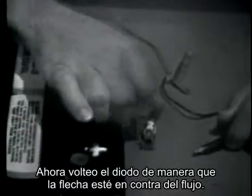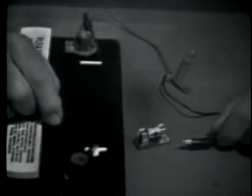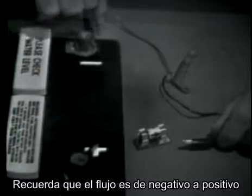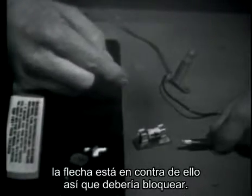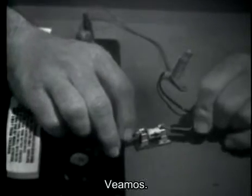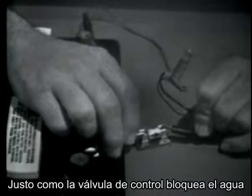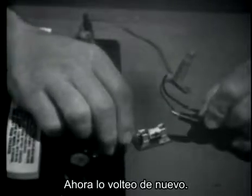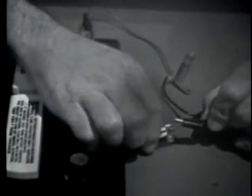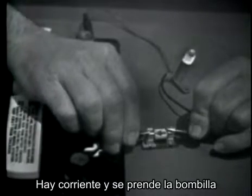Now I'll turn the diode around so that the arrow is against this flow. Remember, if current flows from negative to positive, the arrow is against that, so it should block it. Let's see. Making the connection, the bulb doesn't light. So just as the control valve blocked the flow of water, this diode is blocking current. Now I'll turn it back around again. Current flows, and the bulb lights.